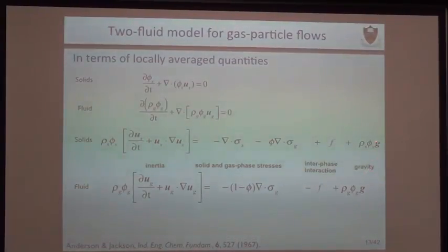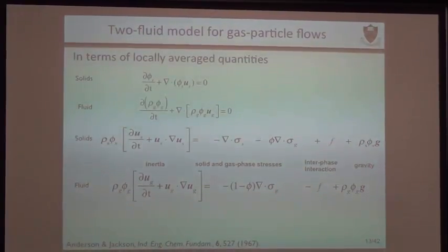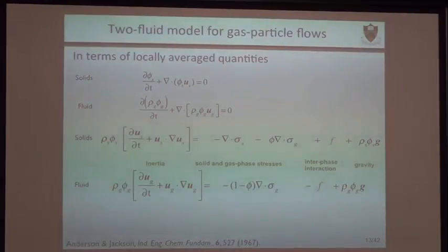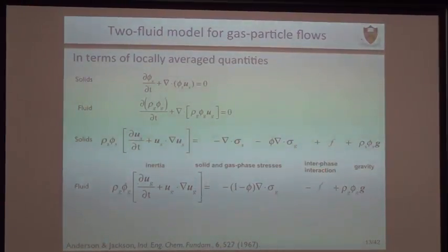And on the right-hand side, you have the gravitational force acting on the gas or the particle. And because they're sharing the same space and they're flowing together, they're talking to each other, and so they're exerting an equal and opposite force on each other. And that's what we call the interphase interaction force.